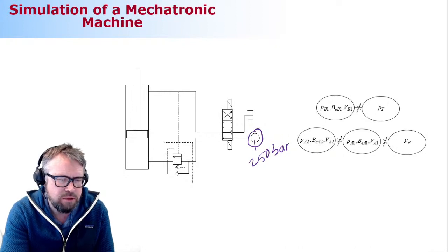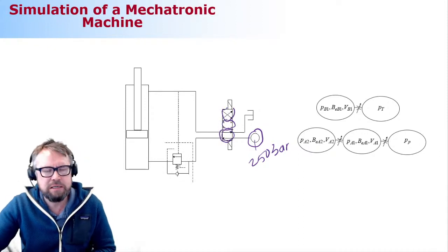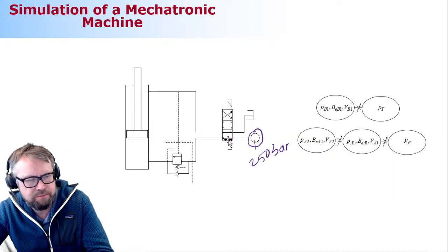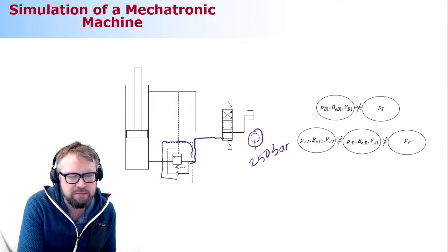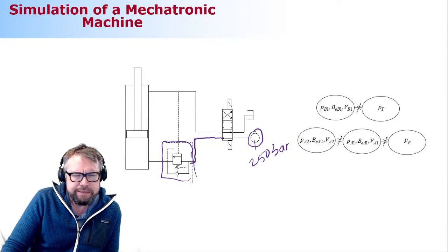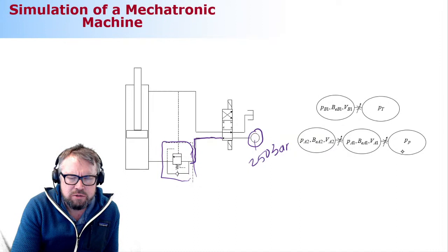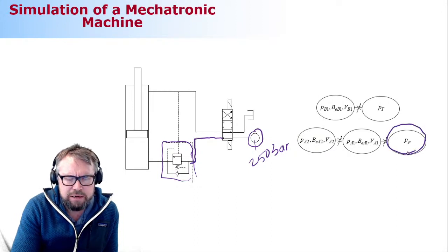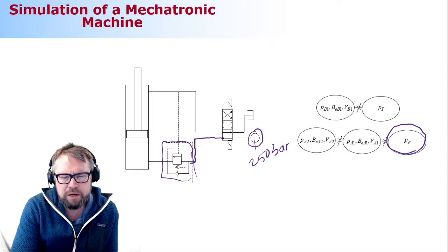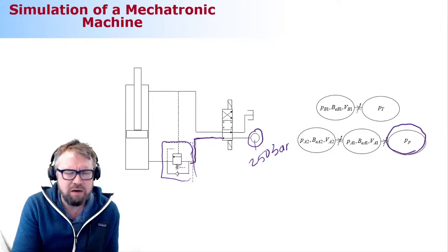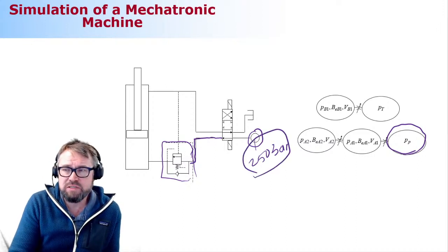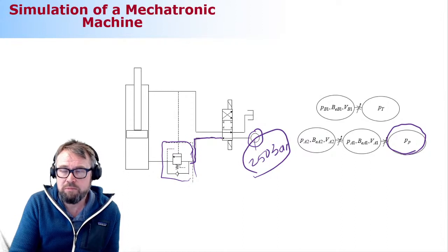A direction valve has three operation conditions, and now I'm selecting the one that is shown here. I think I need to take my drawings off to make this clearer to you. Then right after this direction valve, there's a hose or pipeline that is connected to this counterbalance valve here. Now, if I'm modeling this hydraulic circuit, I can say that the pressure source described here is one place where I need to take pressure into account, not much to compute, because I know it's going to have the same pressure all the time, 250 bars, simple like that.